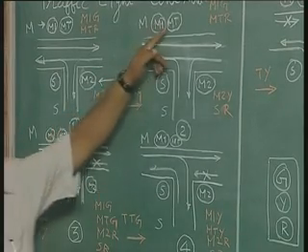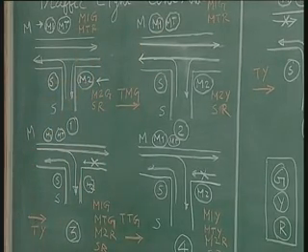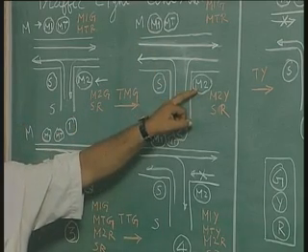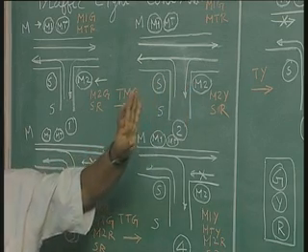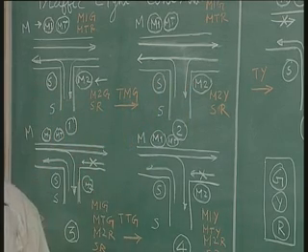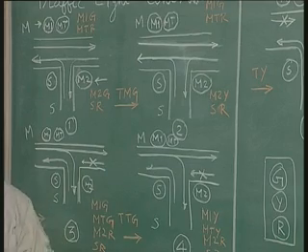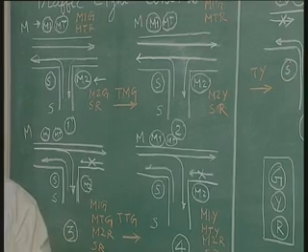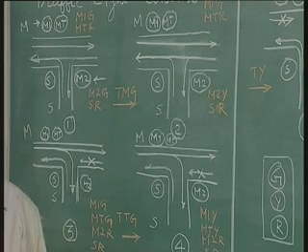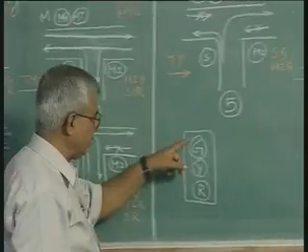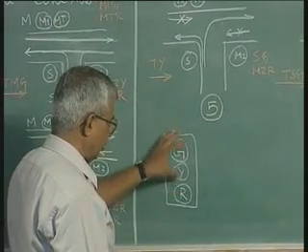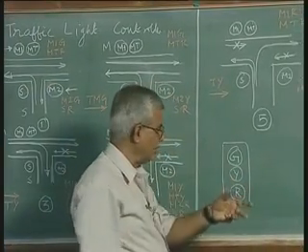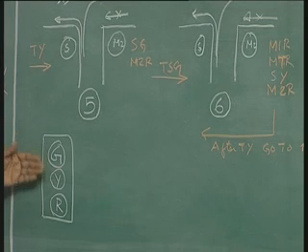That means we should prepare to take MT to green, but I can't do that abruptly, because in order to do that I need to make M2 red. I can't make M2 red from green suddenly, because that will create problems for people traveling at high speed. So you go through an intermediate light called amber or yellow. Each of these lights, M1, M2, MT and S, is fitted with three independent lights: green, yellow, red.